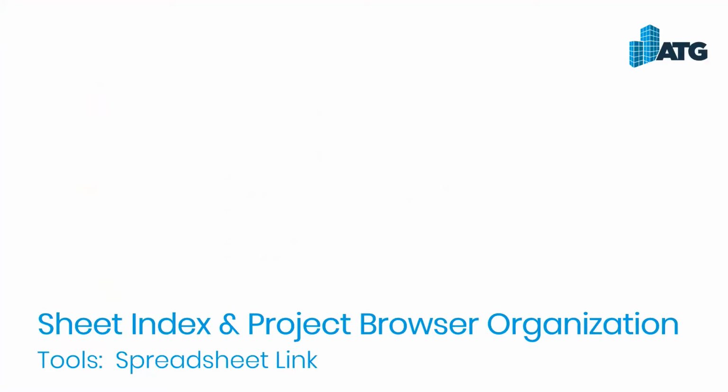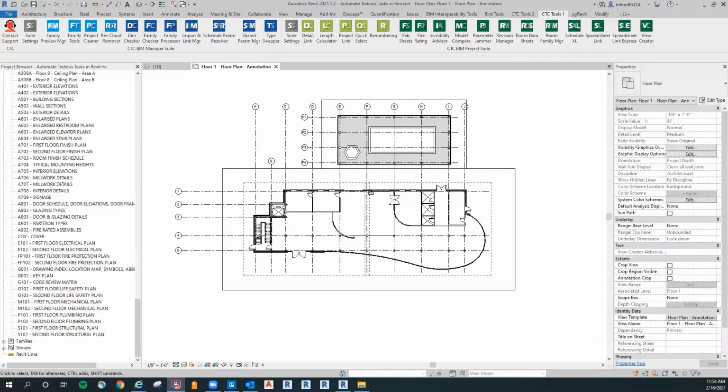All right, so now that we have our sheets mapped out, let's create a sheet index that we can end up populating onto our cover sheet. In addition, I always like to organize my sheets by discipline in the project browser. And from what I've seen, most of the AEC industry follows the same logic. Okay, in this one, we will use Spreadsheet Link again.